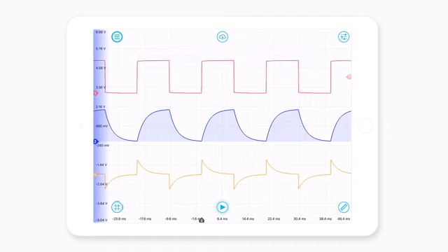You'll notice now that there is a little icon down the bottom of the screen with a play symbol in it. Basically, once we've tried to save data, it has paused the current measurement on the screen. And the reason it has done this is so that we're certain that this is the measurement trace that we wanted to export. To resume the operation of the oscilloscope, just tap the play button and everything will come back and continue to move.